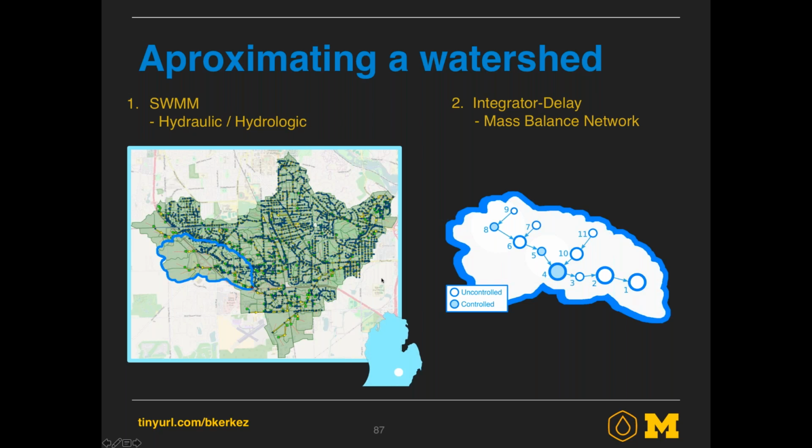And this is what we've been doing for a really long time. We've been making complex models. You can develop a much simpler model that abstracts away only the simple components of the system. So we can take really non-linear systems like these watersheds and represent them as much simpler linear systems, like unit hydrographs effectively, that are adding up on top of each other. And because we're using valves, we can steer the system back to it. So whatever the model doesn't represent perfectly, you can basically correct with valves, which is really interesting, right? So you don't need a perfect model. And so I'll skip the math.